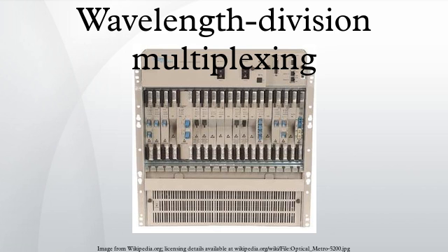EDFAs were originally developed to replace SONET/SDH optical regenerators, which they have made practically obsolete. EDFAs can amplify any optical signal in their operating range, regardless of the modulated bit rate. In terms of multi-wavelength signals, so long as the EDFA has enough pump energy available to it, it can amplify as many optical signals as can be multiplexed into its amplification band.